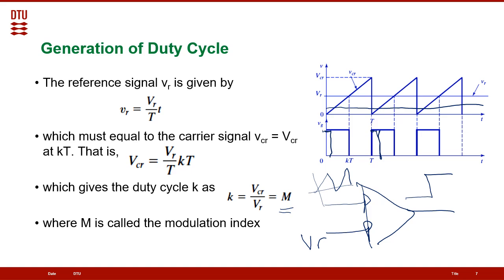In our case, as we are dealing with a buck converter, the frequency of this signal should be in the range of, say, 50 kilohertz and above. By this means, we can produce a variable duty cycle for the converter so that we can control the output voltage.